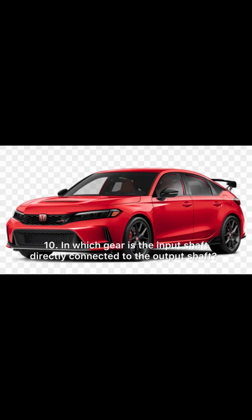10. In which gear is the input shaft directly connected to the output shaft? Fourth gear. 3. When do the output gears rotate freely on the main shaft? All gears except when that gear is locked. 11. Under what conditions does the countershaft rotate? All gears when the engine is running and the clutch is engaged.